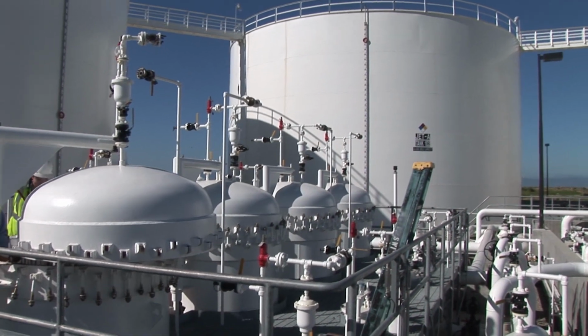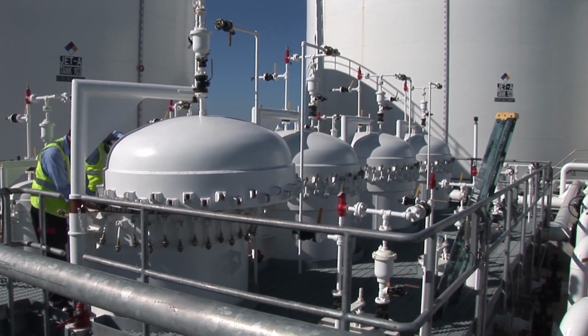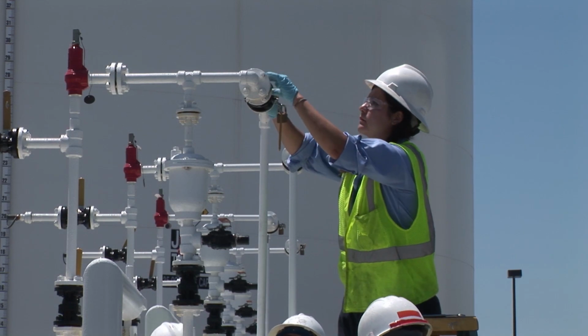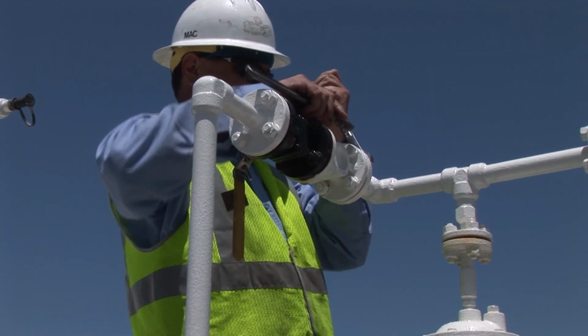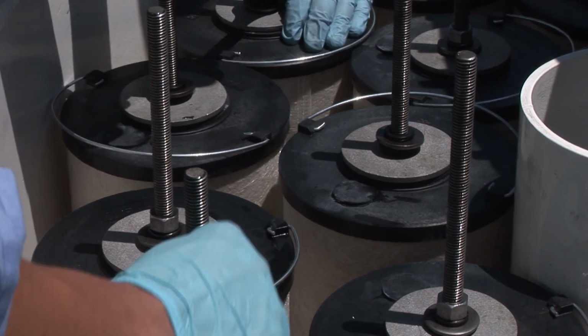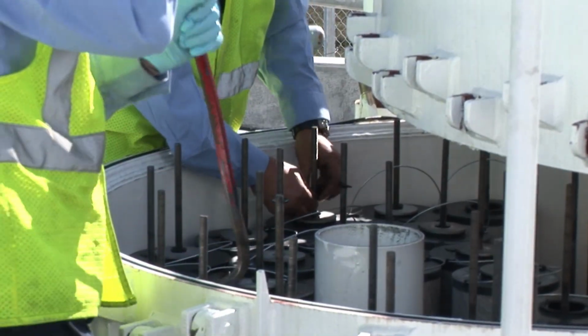This is a clay treater. It's used to combat the surfactants found in jet fuel. Without treatment, surfactants will accumulate and reduce the water coalescing efficiency of the filter separator. So, like the micronic pre-filter, the clay treater is placed upstream to protect the filter separator.